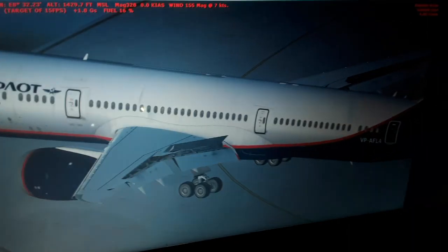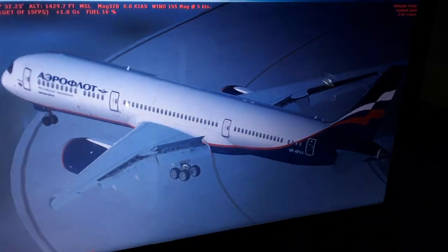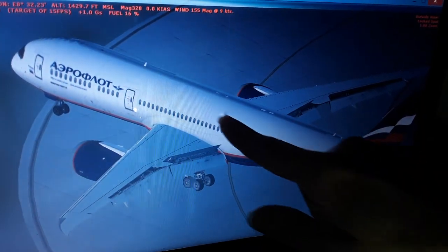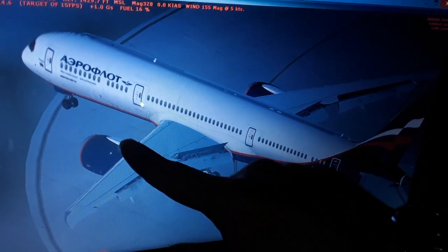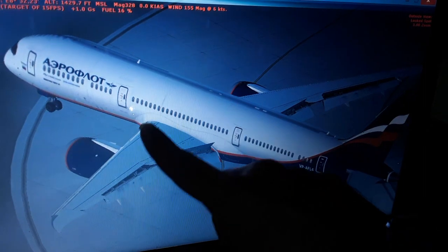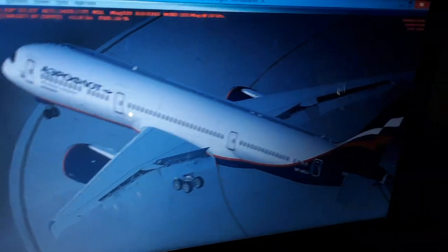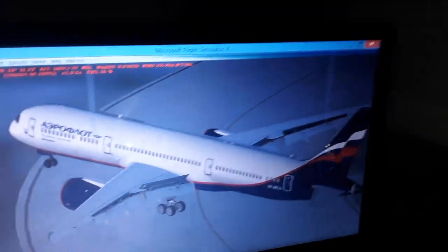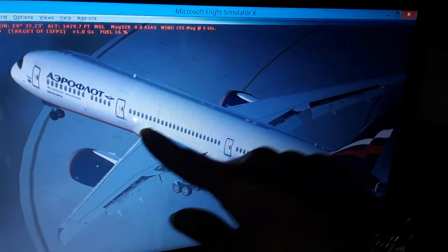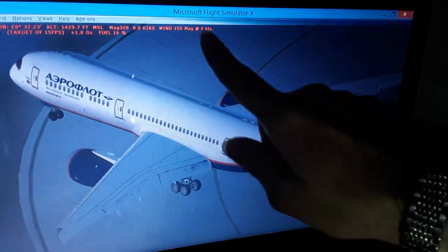and the combustion chamber. We also have the pressurization from the engines coming out to the manifolds over here for the hydraulic fluid tanks, and also cabin pressurization, oxygen, and wing and engine ice protection coming back to the leading edge of the wings and the nozzles of the engines. So we have here the mean aerodynamic chord position where the maximum aerodynamic lift occurs, 33% of the MAC, where the center of pressure moves back and forth, also the center of gravity here.